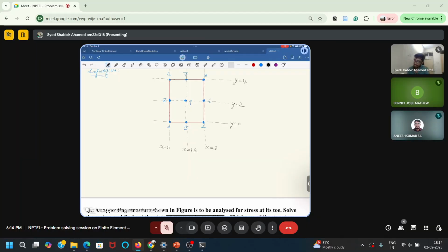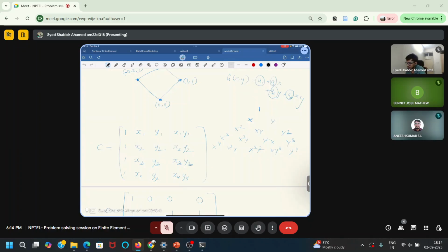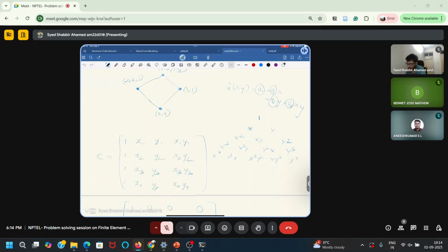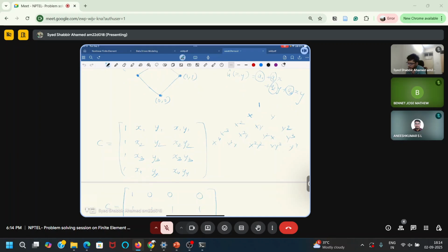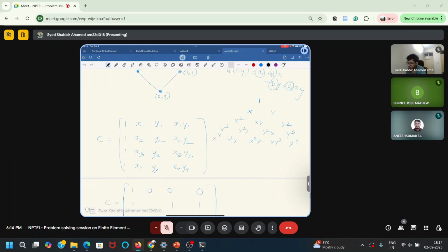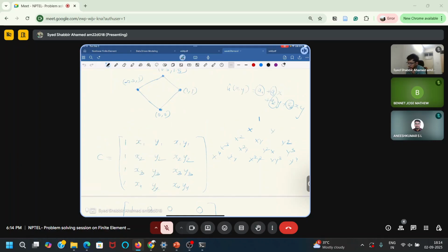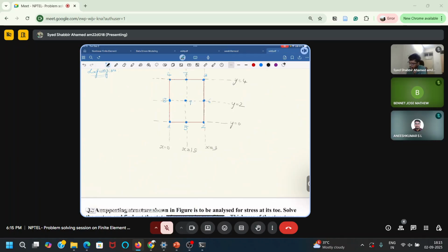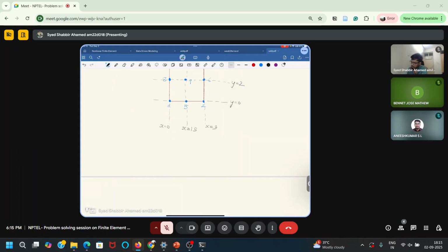Now, last week itself, we have seen how we can derive shape functions based on the approach. There was a four-noded quadrilateral like this. For any shape or any element, we first have to take the coordinate matrix, and we take the terms in this coordinate matrix based on the Pascal triangle. So first we will draw the Pascal triangle and look at how we can select the terms.